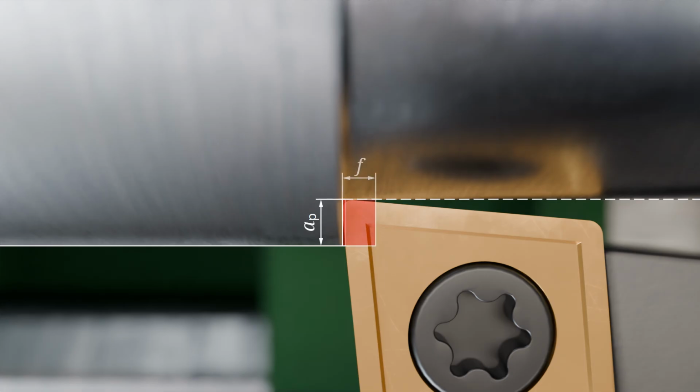The feed rate, however, has a much greater impact on the tool life. Especially high feed rates increase heat generation and thus thermally stress the cutting edge strongly. Large feed rates therefore not only reduce the tool life but also worsen the surface quality due to relatively large feed marks on the workpiece surface. Too low feed rates during finishing may cause very long chips, which can also damage the surface.